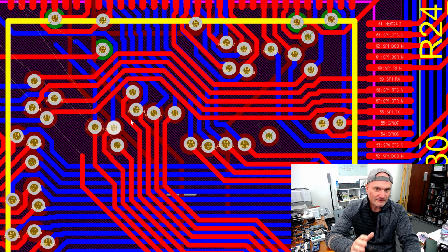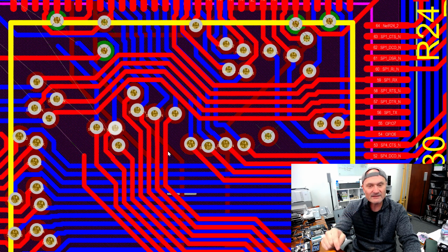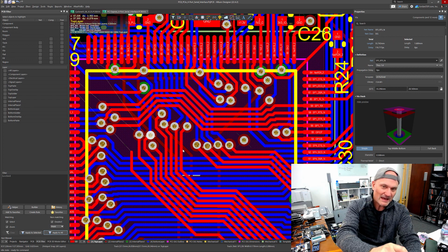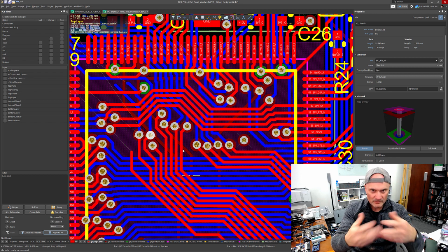So if you're coming from some of those other EDA tools, it is possible to do things the way you're familiar with if you want to. You can predefine pad stacks according to the IPC standard, as we've seen. And you can even create pad and via libraries if you want to reuse things or take it from a manufacturer who says, if you use this pad stack, you can work with that and we'll be able to produce your boards for you with good yield.